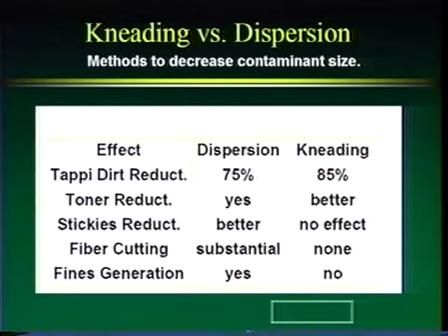Toner reduction, yes, dispersion will work. Kneading is actually better. So we get a better efficiency in toner breakdown with the kneader. Stickies reduction, the disperser actually does a better job here because of the intense metal to contaminant contact action. So stickies reduction is better for dispersion. Kneading, many studies have shown no effect, but that's kind of controversial. And when I say better for dispersion, what I mean is that there's more reduction occurring. It may not necessarily be better.